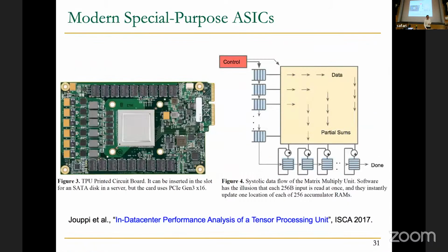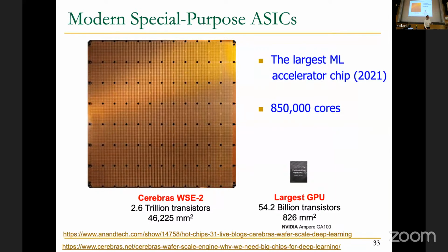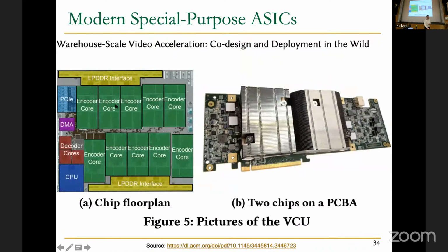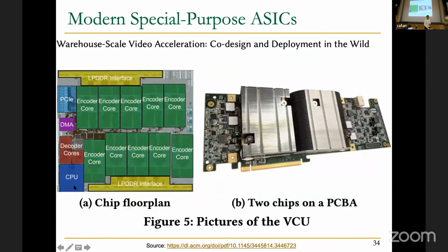And these are the more special purpose chips. And this is another special purpose chip, a systolic array-based chip just for machine learning, as we discussed. It's a TPU. And then these are some examples that we've also seen. And then there are other special purpose ASICs for video, as you can see. And you can also see that there's heterogeneity in these chips. There are CPUs. You can actually do general purpose computation in many of these systems today, because there's usually a CPU in there, but that CPU may not be very powerful, because the goal in this particular case is to do video encoding and decoding. There's a CPU to make sure that runs well. You could also use it for computation, but because it's not powerful, it's not going to be able to compete with a system that's really designed to have very powerful CPUs.